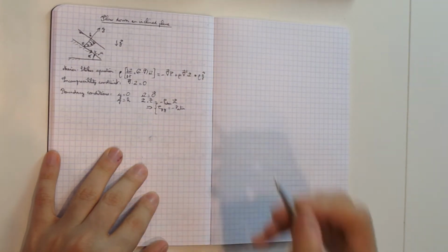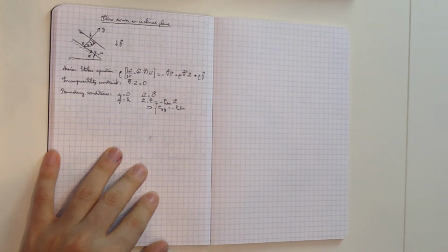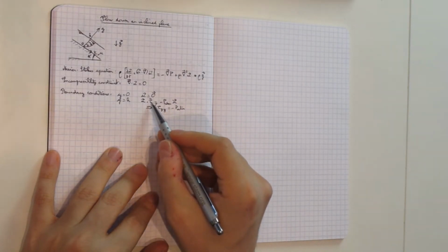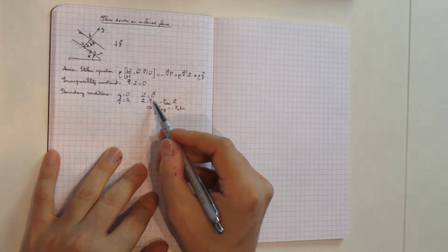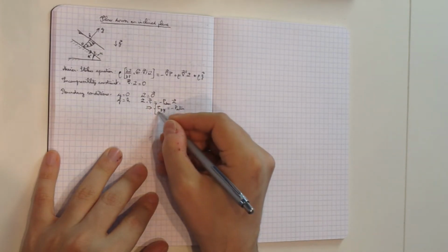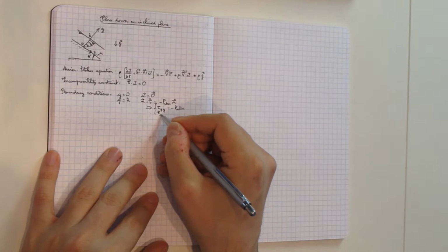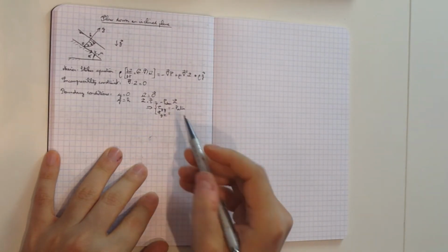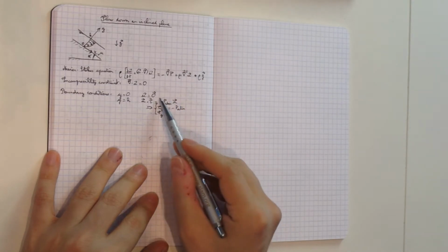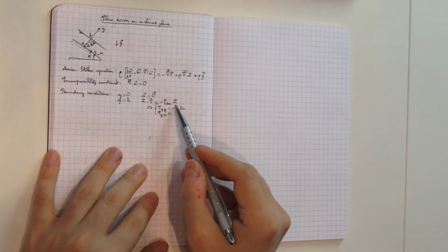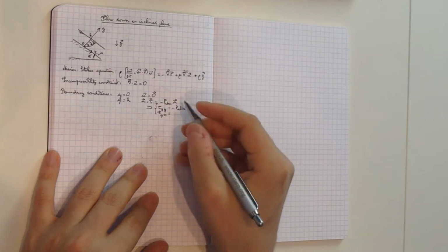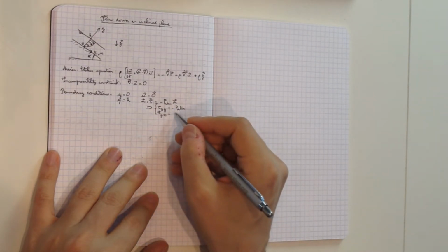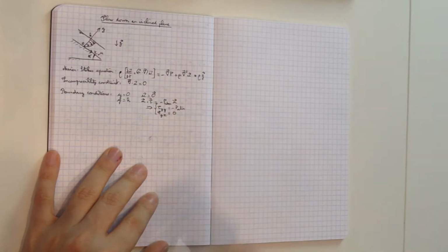And the second stress equation is the one in which I dot the right hand side with the tangential vector, which is x. So that's the tangential stress tau yx, and that's going to be equal to the tangential stress in the air, and that tangential stress is 0 because n dot the tangential vector is 0. So that's going to be 0.